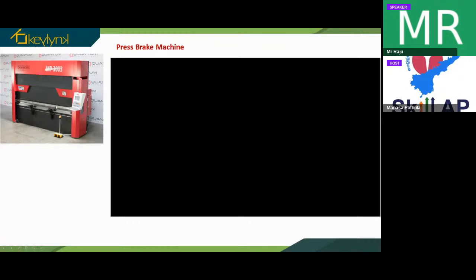Here, this is a press brake machine, which we use for different sheet metal operations. This press brake machine is from the company Nargesa. This is a feeder here, the CNC controller. We'll feed the necessary inputs here, and the dies will be kept at this portion of the machine. And this is the ram. It moves up and down in a vertical motion. We keep the blanks or the sheet metal here, and we feed it. The laser sensor will detect the sheet metal and give the necessary output, the component that we require.